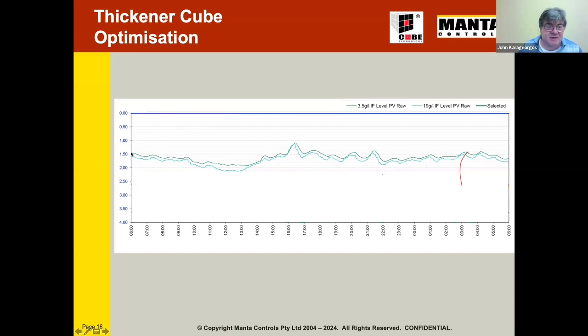Some sites even, we start to worry because this is depth. We use depth, zero at the surface, and some sites were allowing the interfaces to creep up to, in this one here, 1.5 meters, 1 meter. We will not go typically anywhere near above 1 meter below the surface. Some sites we keep them down to 2.5, depending on what it is. So that's really important. And this information you just can't get accurately and repeatedly from any other analyzer in the world at the moment.